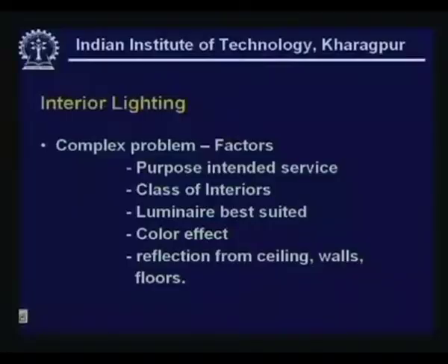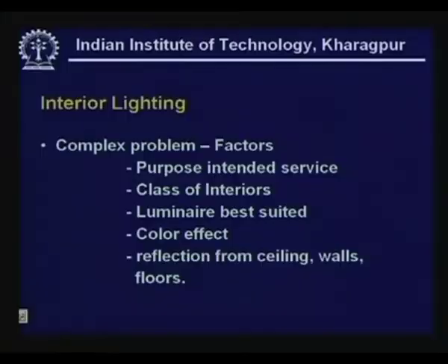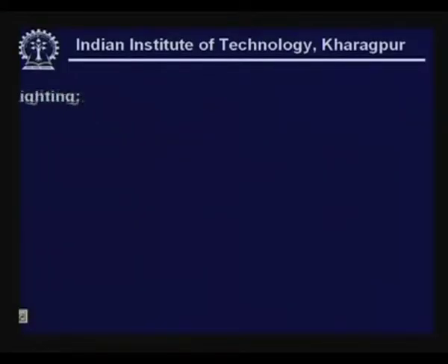And in fact one other issue which becomes very crucial and one of the common mistakes in a lighting design is glare, and that can arise from the reflections. If proper reflection factors are not chosen and the colors of the furnishings vis-a-vis the walls are not matched. These are some of the issues one needs to keep in mind.